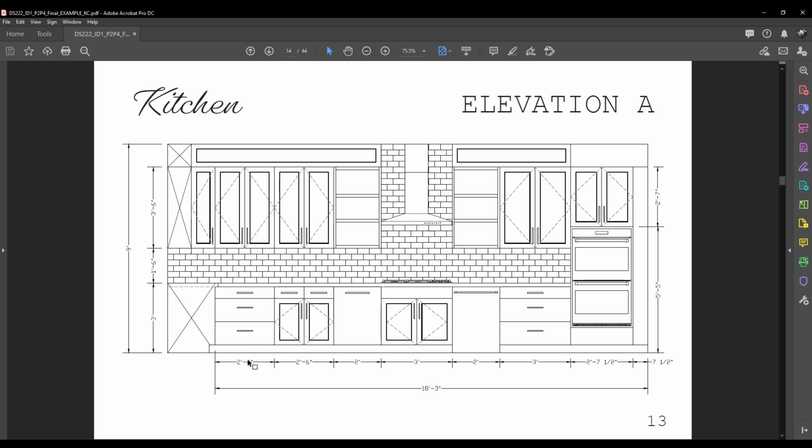As you're thinking about your designs, you also want to be including, of course, the toe kick, right? There'd actually be a toe kick across the dishwasher as well, right? We're thinking about including all of the relevant information about the 36-inch high countertop, the 18-inch backsplash under these upper cabinets, the height of the upper cabinets, the full 9-foot height of the room, right? And then showing the sizes of the cabinetry.